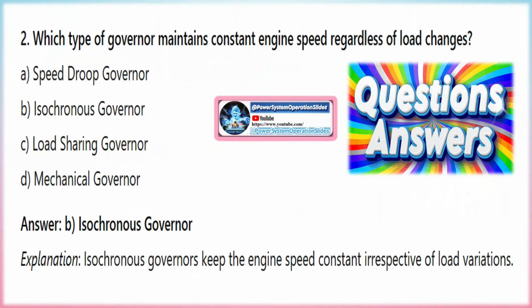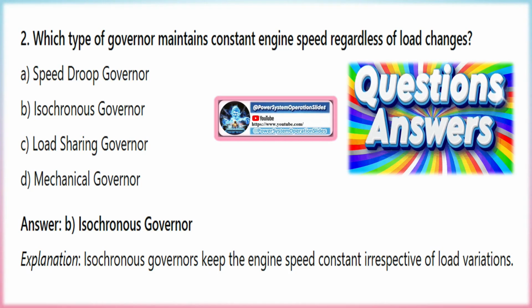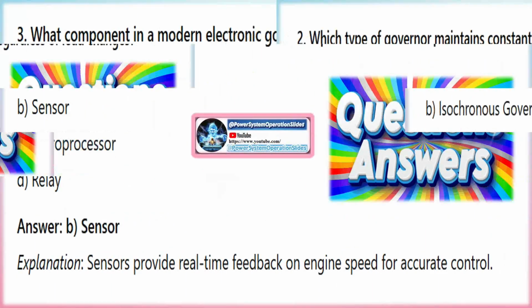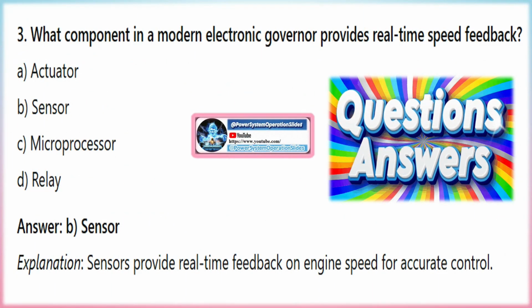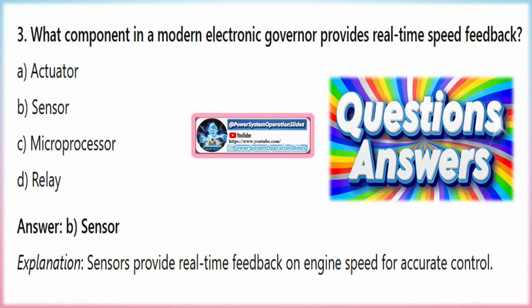The modern power governor is a critical component of AGC, providing the fine control necessary to balance generation and load in real time. Its ability to adjust generator output quickly and accurately in response to AGC signals helps to maintain system frequency, ensure power quality, prevent cascading failures, and enable efficient power sharing across interconnected grids. The integration of advanced control features and communication interfaces further enhances the governor's role in ensuring the reliability and stability of modern power systems.